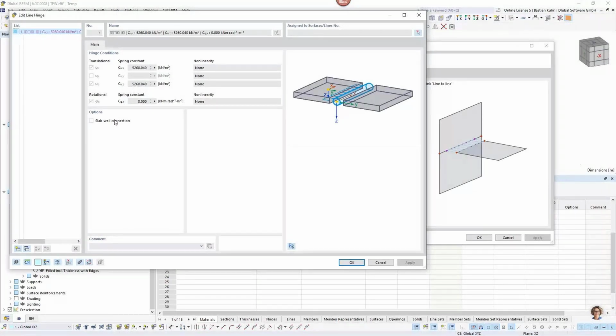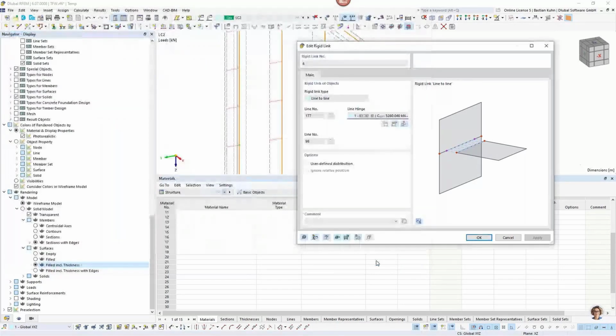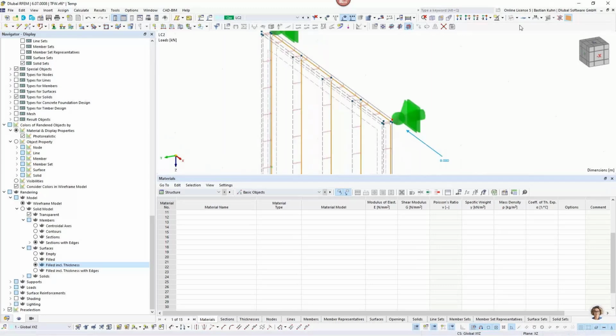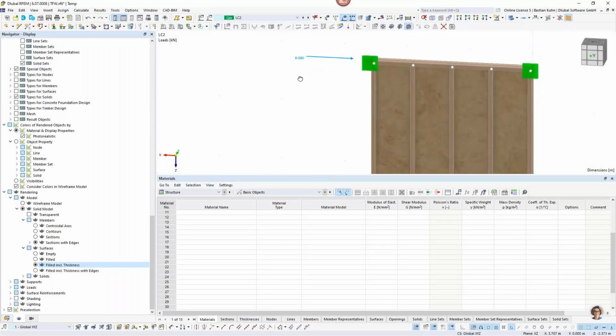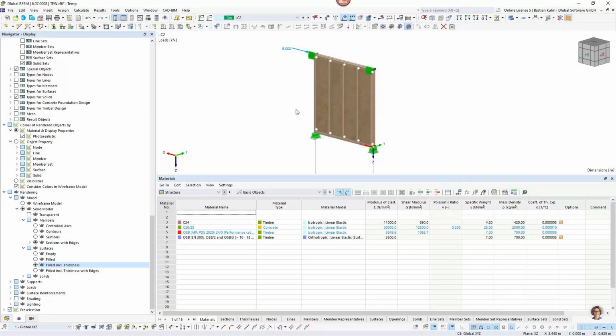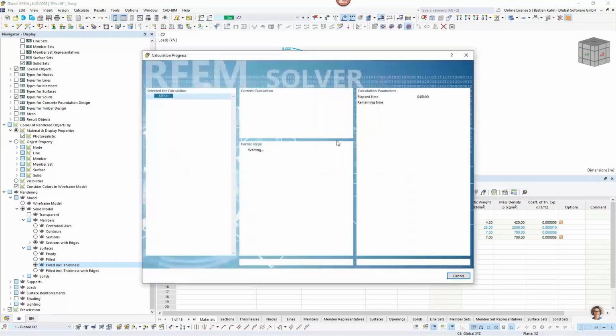I also told you that we should remember this longitudinal stiffness, where if I had chosen just to have the stiffness in UX direction, my UZ value would be 0 in here. So that would also be possible. Okay, this is the generated hinge, and it's generated once again between each beam and the OSB planking. I will put the rendering on again. Here, this way, it's probably better visibility. Okay, so now we want to see results of it, of course.